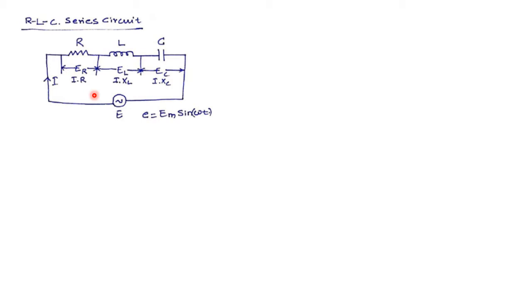So it is difficult for us to say whether the behavior of the circuit is resistive, inductive or capacitive, because the effect of resistance, the effect of inductance and the effect of capacitance are all present. Ultimately, the nature of the RLC series circuit can be known only when I know the values of resistance, inductance and capacitance, and which of the components is prominently having its effect in the circuit operation.